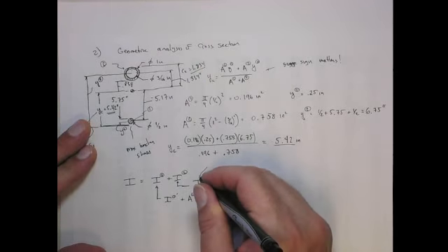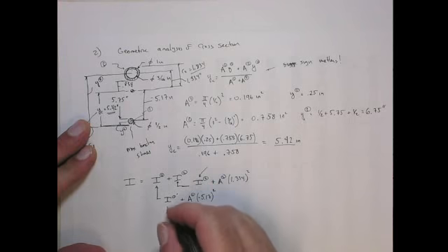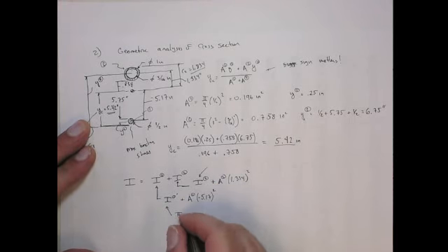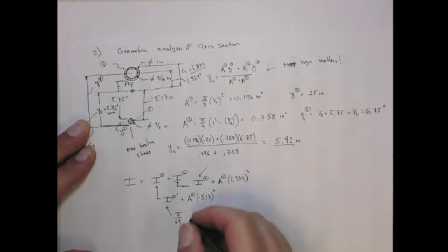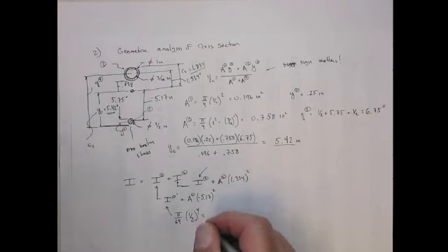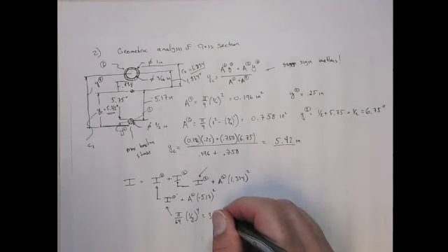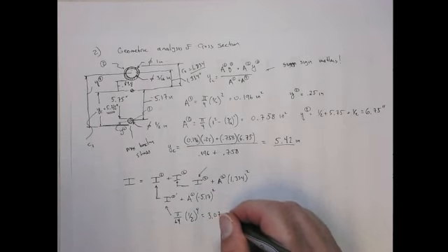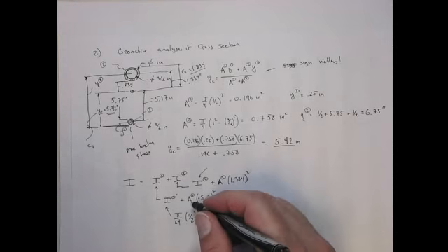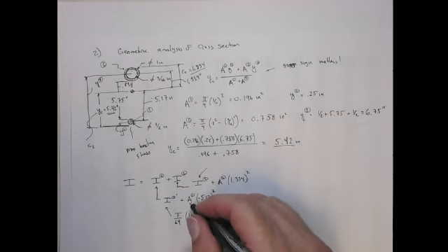We just need to get the I. So this one here, well, let's do I1 just to be consistent. I1 is going to be pi over 64 times its diameter to the 4th. So that's 1/2 to the 4th. And so that gives me 3.07 inches to the 4th.